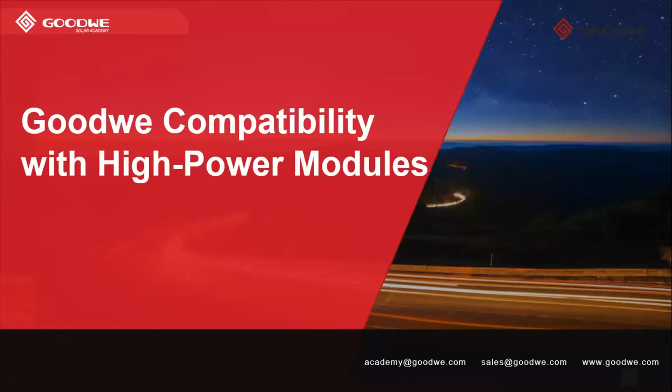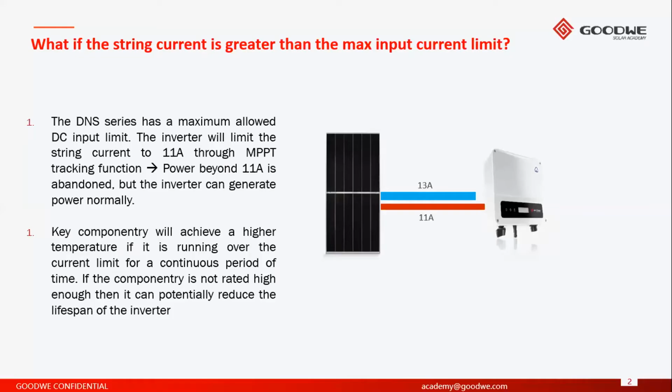Thanks, Ramsey, and good question. It certainly does have implications for an inverter manufacturer. As we've seen the panel and wafer sizes increase over the years, it means that as an inverter manufacturer, we've constantly got to be upgrading our inverters to accommodate those higher currents. And when we're talking about upgrading, we're talking in particular about the maximum input current of the inverter. So I'll just share my screen with you.